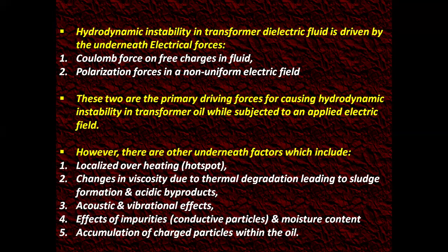However, there are other underneath factors which include: Number 1. Localized overheating, that is hotspot; changes in viscosity due to thermal degradation leading to sludge formation and acidic byproducts. Number 3. Acoustic or vibrational effects. Number 4. Effects of impurities, that is due to conductive particles and moisture content. Number 5. Accumulation of charged particles within the oil.